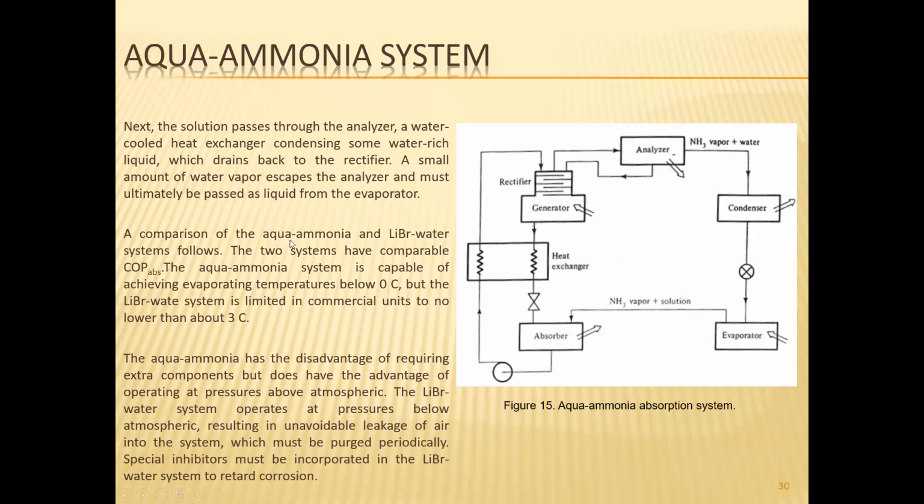A comparison of aqua ammonia and lithium bromide systems follows. The two systems have comparable COP. The aqua ammonia system is capable of achieving evaporating temperatures below 0 C, but the lithium bromide water system is limited in commercial units to no lower than about 3 C.